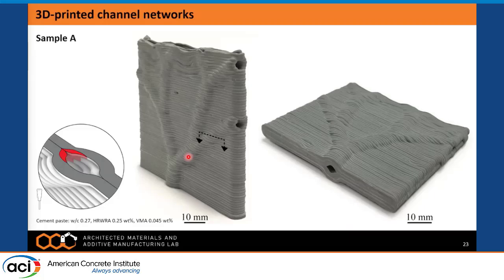Due to its somewhat symmetrical design, the script suggested using a toolpath angle beta of about 0 degrees would result in the lowest M values. And after printing, we could indeed see that the channel openings on the side and bottom of the print remained open.